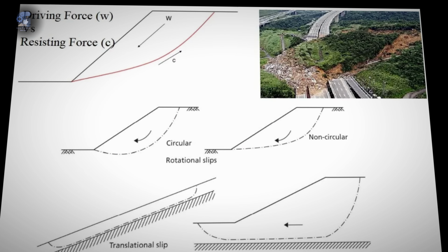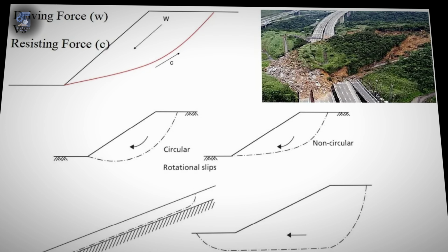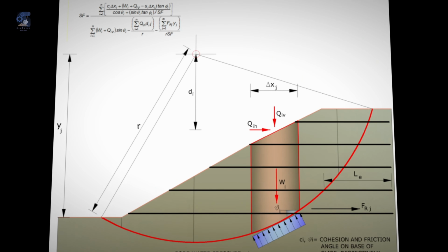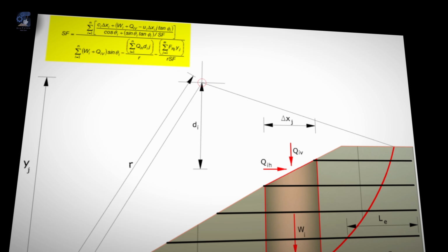As for slope stability assessment, practitioners traditionally use limit equilibrium methods to calculate the factor of safety. Many design parameters are calculated using correlations derived from regression fitting of historical datasets, often requiring expert judgment to apply correctly. As computational power increased, more sophisticated methods were integrated into the field.